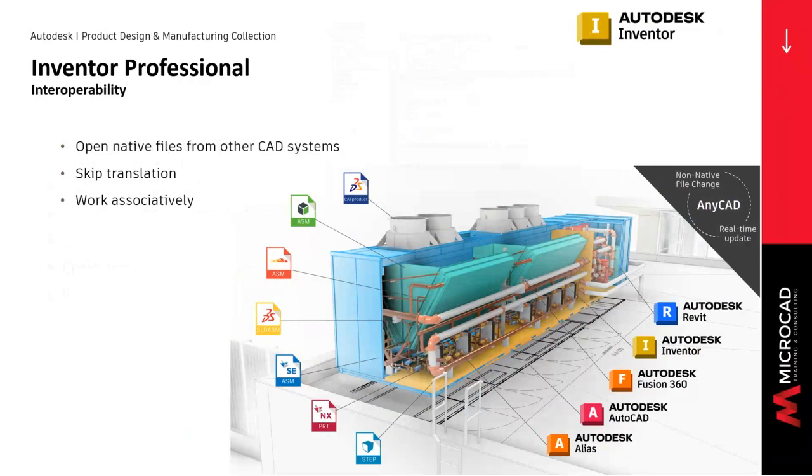You can simply open the file and maintain it in its original form and associate it and link it to your design. If any changes are made, the model just simply updates. If I have a SOLIDWORKS part file in my design and my vendor updates that SOLIDWORKS file, I simply just overwrite what I have and my assembly updates dynamically. I don't have to re-import it, place it, reconstrain it. It just updates dynamically. Anything that I've created around it reflects that and updates appropriately.